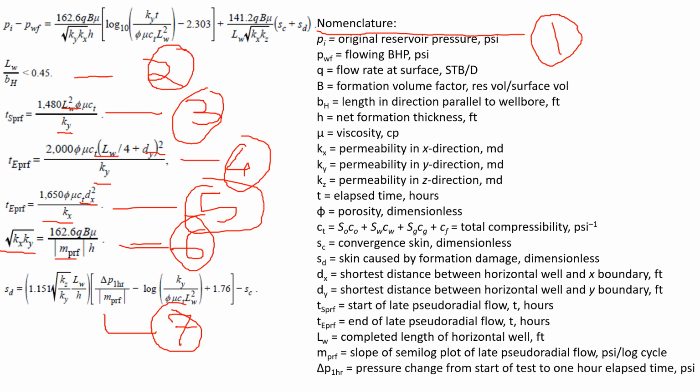Semilog plots of build-up test data from the late pseudo-radial flow regime cannot be analyzed rigorously using a Horner plot unless pressures at tp plus delta t and at time delta t are simultaneously in the pseudo-radial flow regime, which is highly unlikely. However, little error appears if the producing time before shut-in is much greater than the maximum shut-in time achieved in the build-up test.